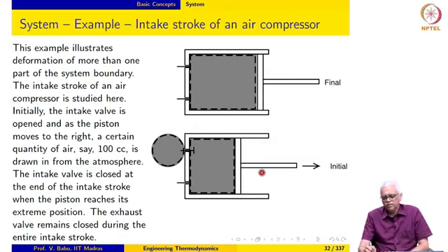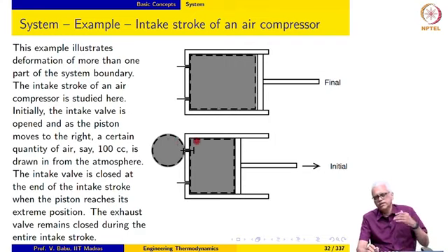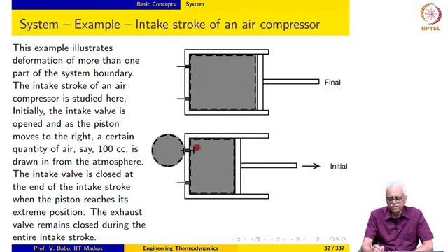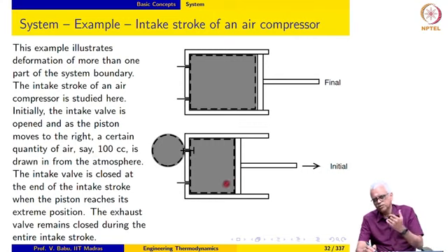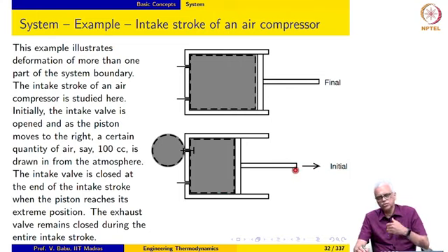Okay. So, we can probably infer that the work interaction in this part of the system boundary is such that the surroundings are actually doing work to push this air inside the cylinder against the resistance provided by the valve. And this part of the system boundary is actually expanding. So, it is doing work against the resistance that is provided at the end of this connecting rod. So, it is connected to a motor or a crankshaft and so on, which will provide a certain resistance.